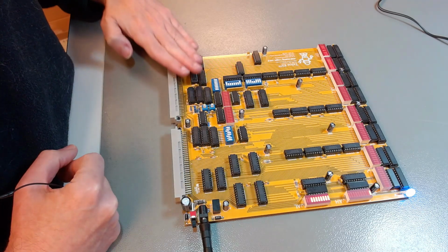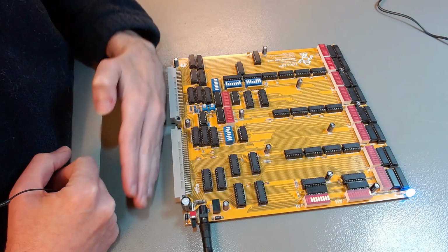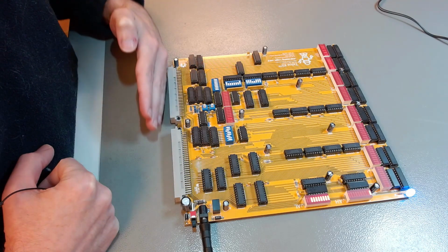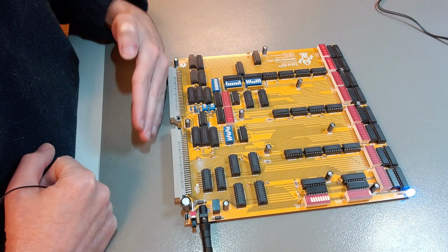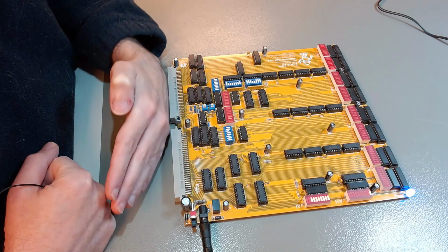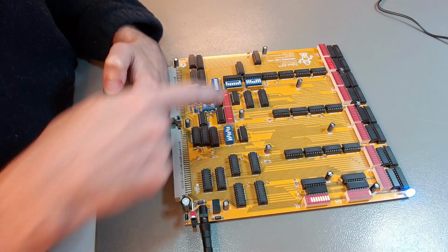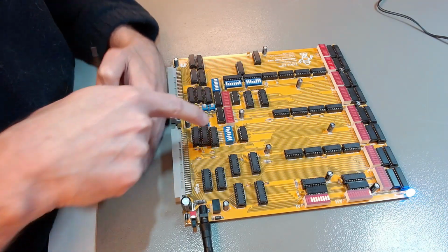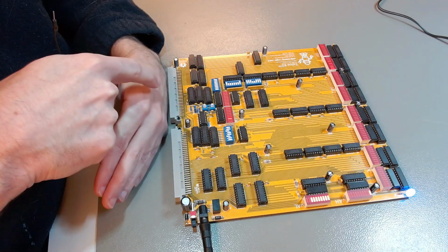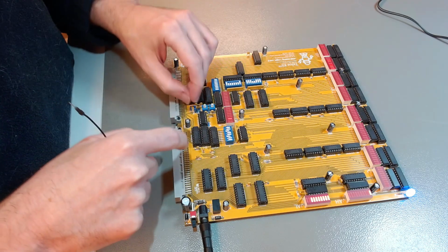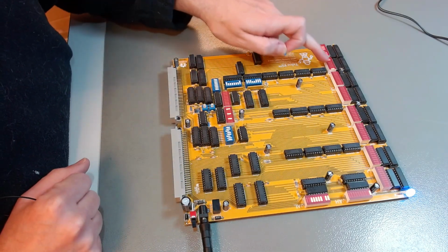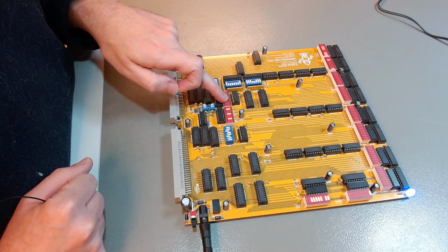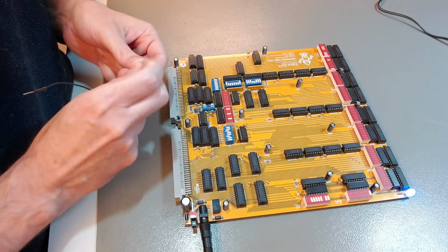If I put my hands on top, you see? If I run my hands close, the pins of the backplane connector pick up the disturbances that the presence of my hand provokes on the electromagnetic fields around here, and you see that disturbance on the LEDs, even in the control signals, which come from around here. But if I disconnect it, then it's again driven by the dip switches. The bus is driven by these dip switches, and the control lines driven by these two dip switches.